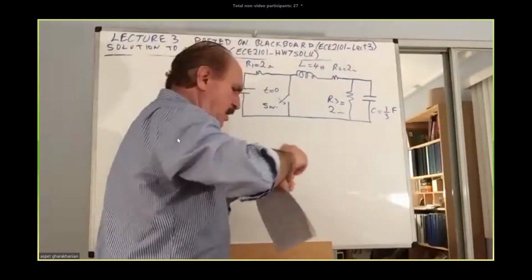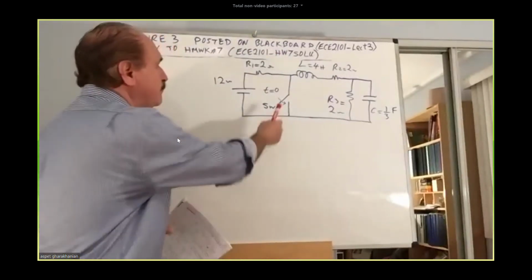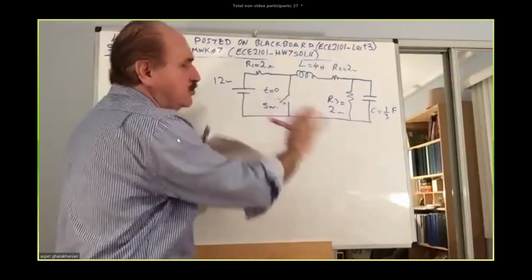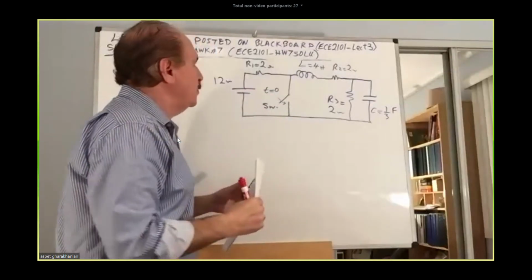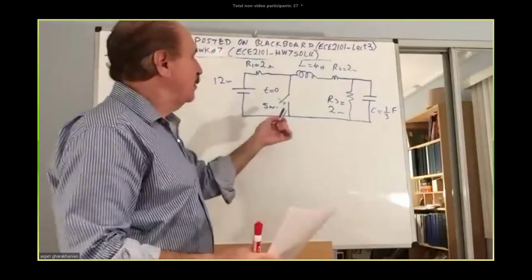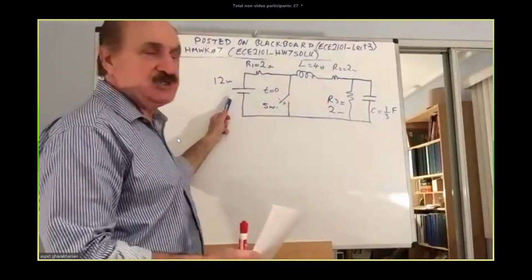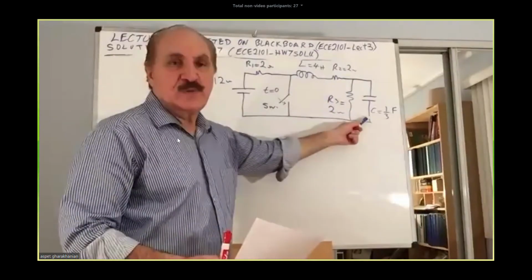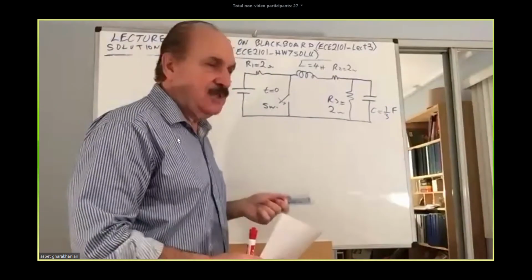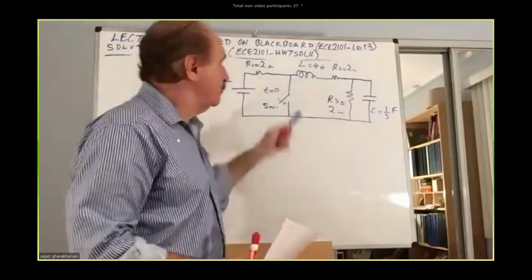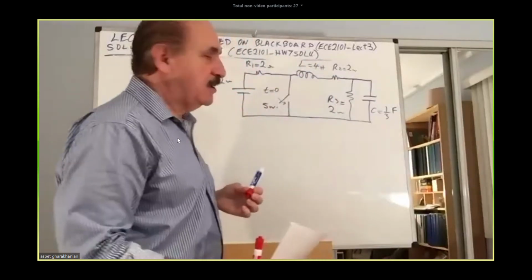Okay. So the switch is open. The circuit is at rest, at steady state condition. In other words, the same old story. Inductors are short circuit at the steady state because the battery is a steady source. Capacitors are open circuit. Being a short, it doesn't mean its current is 0. There must be a current running through it because you have a circuit. So a current is going through it.